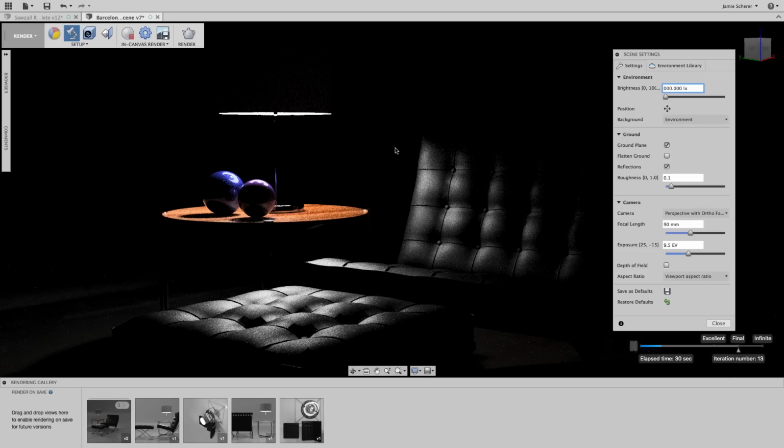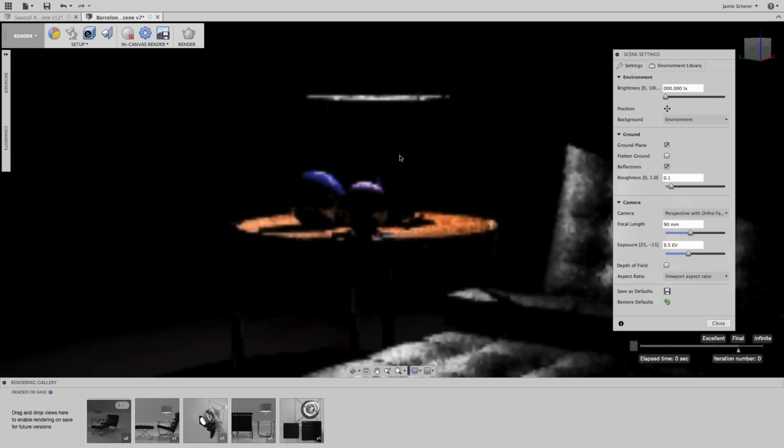And oftentimes someone will ask, what about lights? Are there ways that I can set up lights? The answer is absolutely. Grab a sphere, a primitive, a cube, put it in space, and make a realistic light source. You don't have to make a cone light or something like that. Make the realistic lights that are in your scene. You'll get higher quality renderings by doing it.